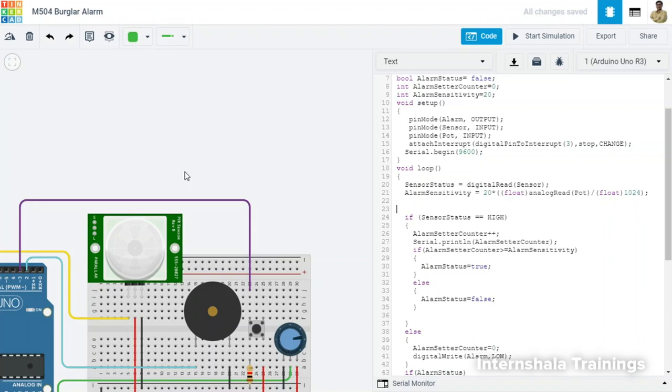Then I say, fine, I am going to keep that and start a counter. Detection number 1, detection number 2, 3, 4, because false alarms like movement of wind or some curtains near the sensor or anything like that can also trigger your PIR sensor. So I am saying that it should not get triggered by minor movements. If there is a major movement, that means the number of detections is more, so I will keep counting them.